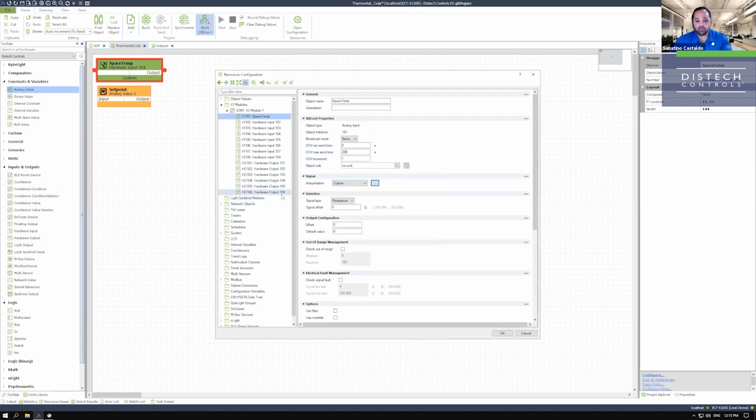This is a true BACnet COV. It's the object itself. It's not trying to realize or proxy with anyone else. It's communication on the bus. So if I tell it you have a 5-second throttle on your min send time, then you're not going to send anywhere faster than 5 seconds, even if you change more than that.